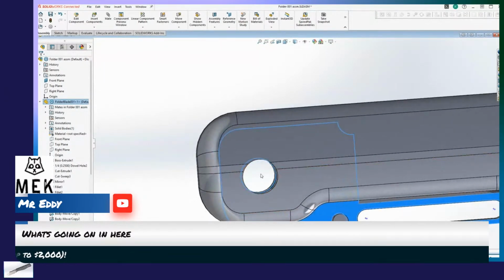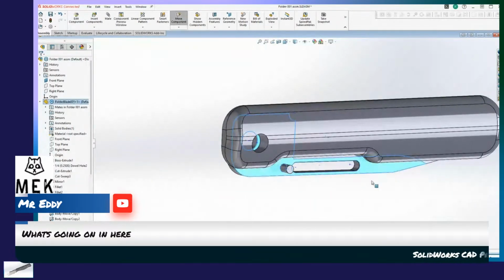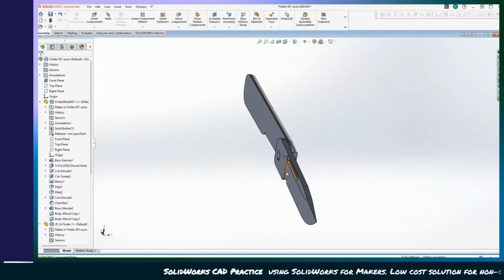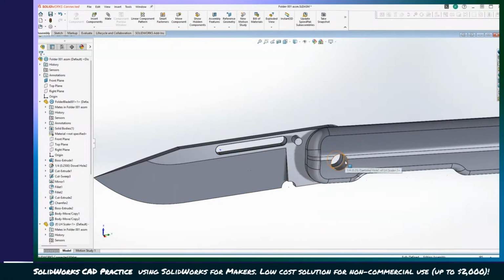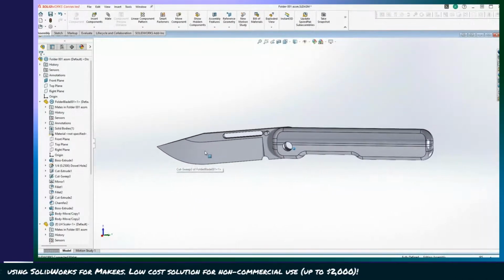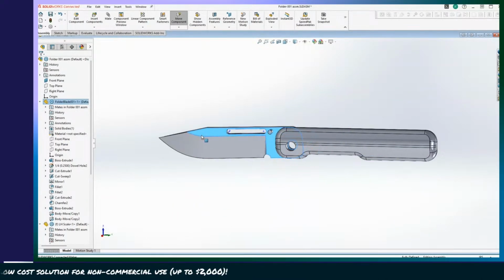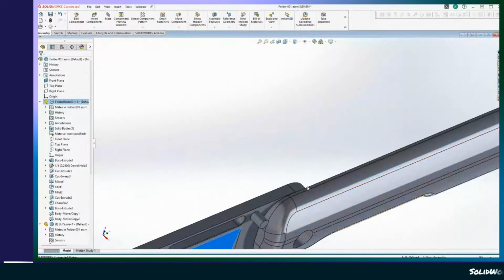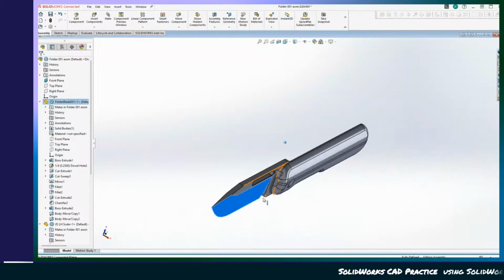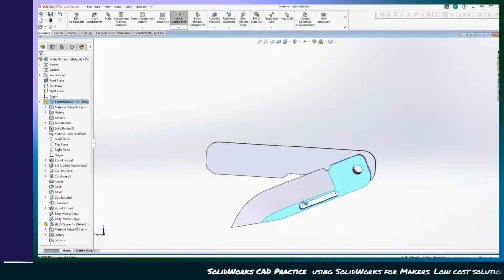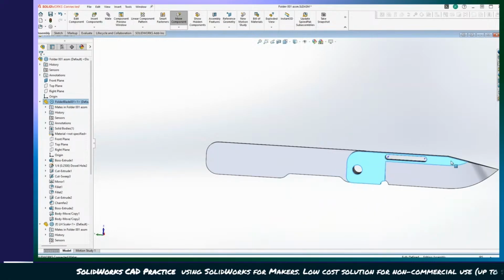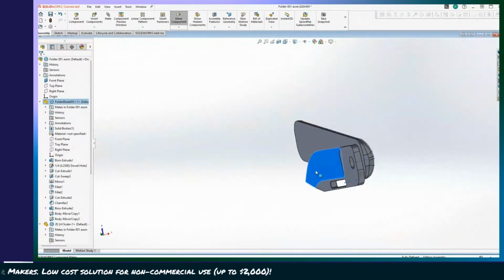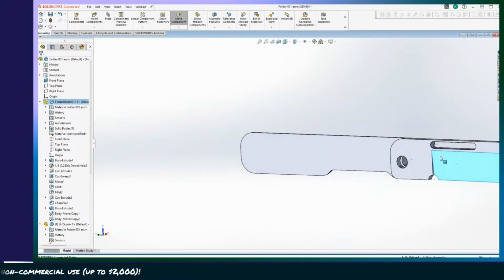Put a rotational constraint, move constraint in this assembly. And right now the assembly is just one scale and the blade. I put a pocket in one scale for the bearings, and then we put the rotational constraint and then also an angular limit. So from this surface to this surface, from 0 to 180 or 180 to 0, however you're looking at it. Just so it's easier to analyze the assembly as we go.